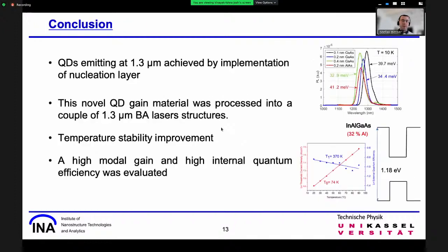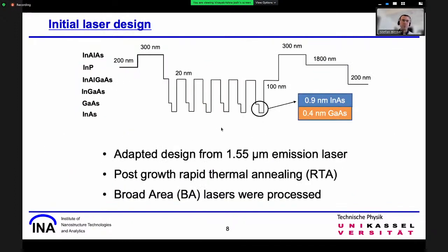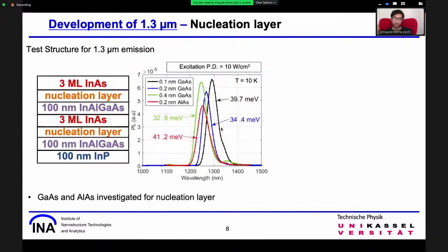Are there any other parameters of the growth process or the epitaxial structure that you think you can improve further? In the growth processes, we can, of course, change the barrier layer condition by checking its growth temperature and even the V/III ratios of the barrier layer, as the nucleation layer will be on the barrier layer, which will create the nucleation points for our quantum dots to grow on. So currently the barrier layer hasn't been investigated as much. So probably that would also be into consideration, taking into account that that will be the growth condition for the upper layer of the active region.